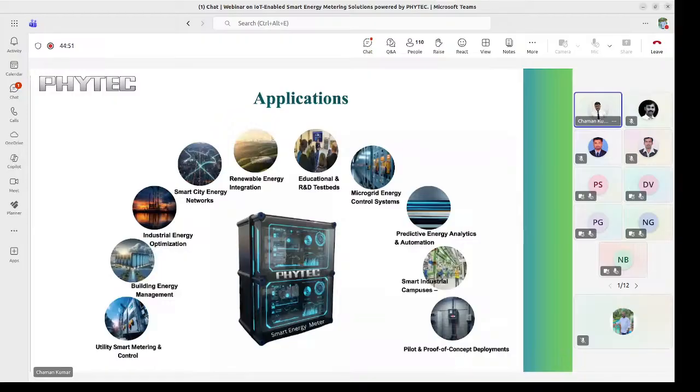And if you go for the RF mesh network, all of these are meters, so we have different smart meters. Now each smart meter wants to send the data to the head end system and then the utility. How will it send? It will not send directly, because in this RF mesh, each meter has its NIC card, the network interface card, which sends the data over RF. The range of radio frequency is basically 500 to 600 meters. Within that local area network, it will send the data to the DCU.